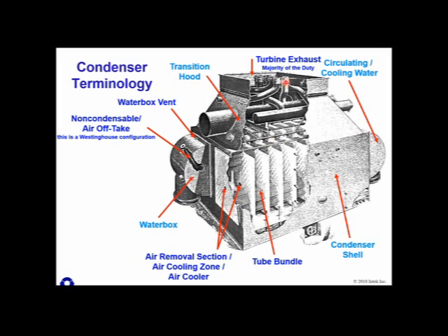The last term is the duty. Really heat duty. The majority component of the heat duty to the condenser, or the heat load to the condenser, is the turbine exhaust, but other things like the boiler feed pump turbine exhaust, drains, high temperature drains, can all add to the thermal duty, the heat duty to the condenser. But the word duty is the thermal load on the condenser that gets transferred to the cooling water.